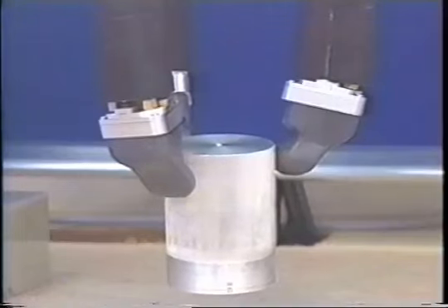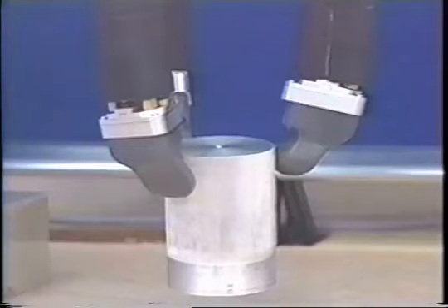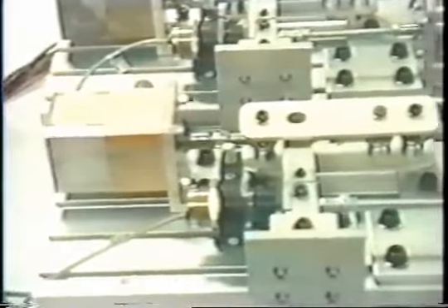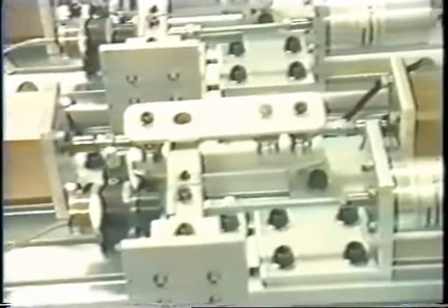The hydraulic proportional valves used for this control have limited bandwidth with deadband and hysteresis. A prototype electromechanical valve has therefore been developed for high bandwidth vibration damping. With a sliding mode approach, dynamics up to 6 Hz have successfully been controlled.